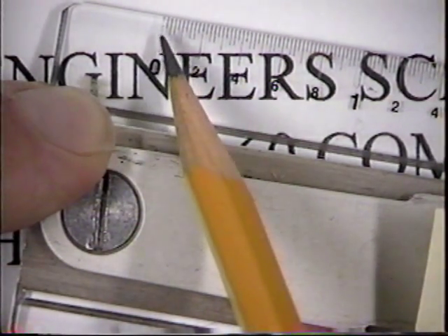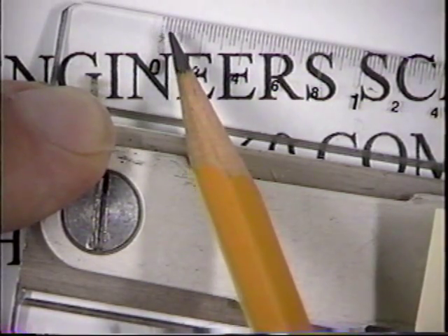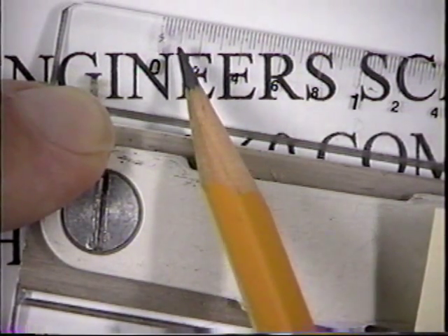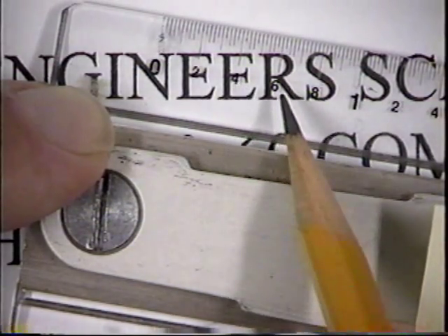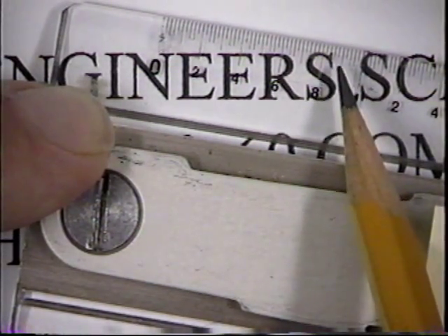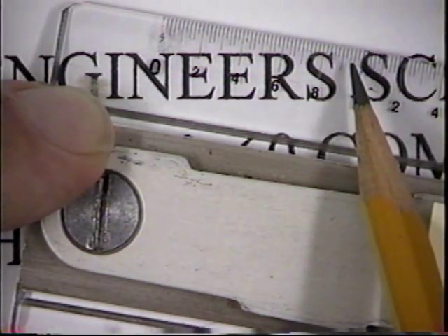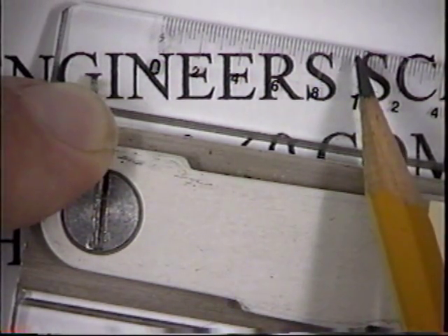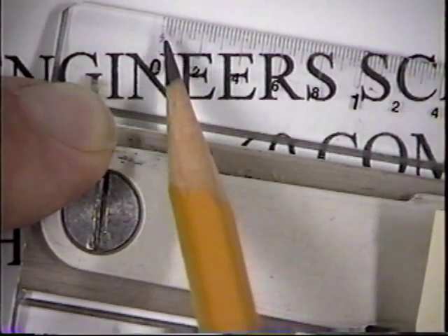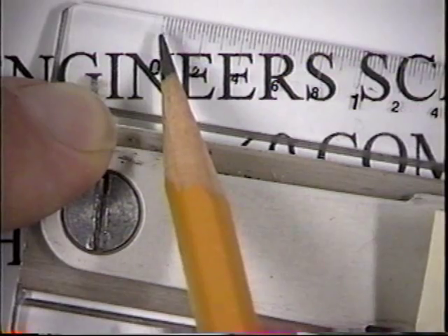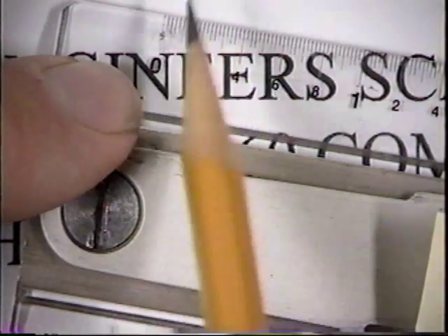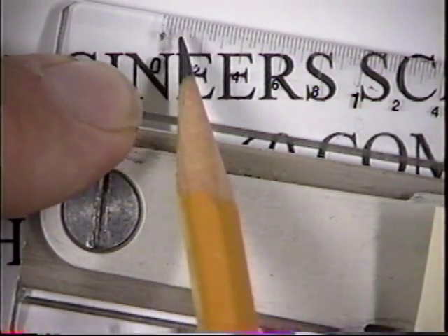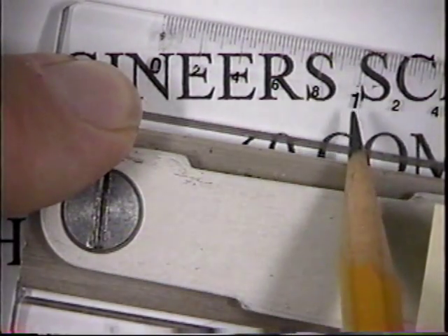Alright, here we have 0. You can see the 0 mark. There's 0.2, 0.4, 0.6, 0.8, and there's a 1/10 of an inch. So we've got a 1/10 of an inch, 2/10, 4/10, 6/10, 8/10. There's 9/10 of an inch, 9.2, 9.4, 9.6, and the smallest unit before 1 inch is 0.98. Now the reason we need to know the smallest unit is so we can always understand how we can discriminate the measurement. And the measurement here that we can discriminate to is 0.02. So 0.02 is our smallest discrimination when we have 50 marks or 50 units in 1 inch.